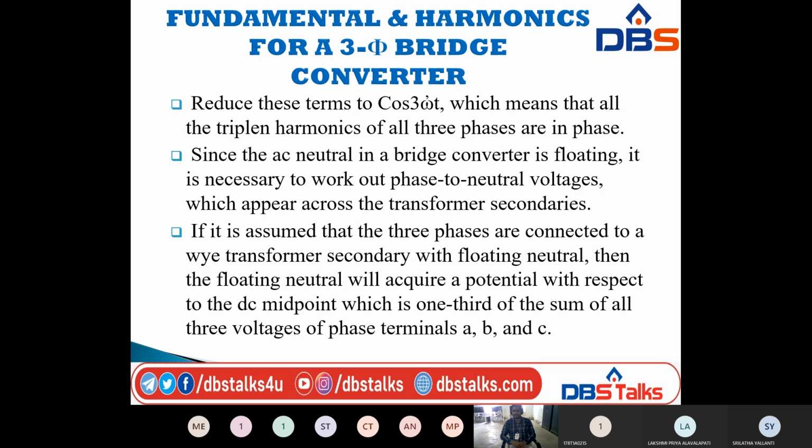Since the AC neutral in a bridge converter is floating, it is necessary to work out phase to neutral voltages, which appear across the transformer secondaries, that is, on the AC side. So we are taking the transformer at the AC side only.